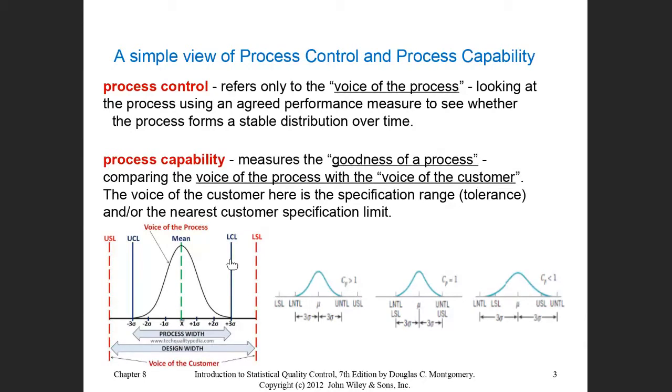You remember we had many times points exceeding the control limits, or even if they are not exceeding, they may have out of control cases based on the 8 rules or the 4 rules that we have covered. Imagine that every time you have an out of control point, that means you are out of the specification.